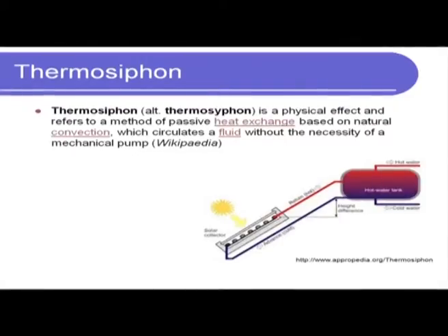What is the difference between a heat pipe and a thermosiphon? Okay. So, a thermosiphon works completely driven by density difference. One of the most common examples that I have seen is our solar water heaters, where the cold water gets heated in the solar collector, and because its density is lower, it goes to the tank, from where we can get hot water. And then again the cold water comes back and is heated in the loop. So, the entire flow happens due to density difference, completely natural circulation.